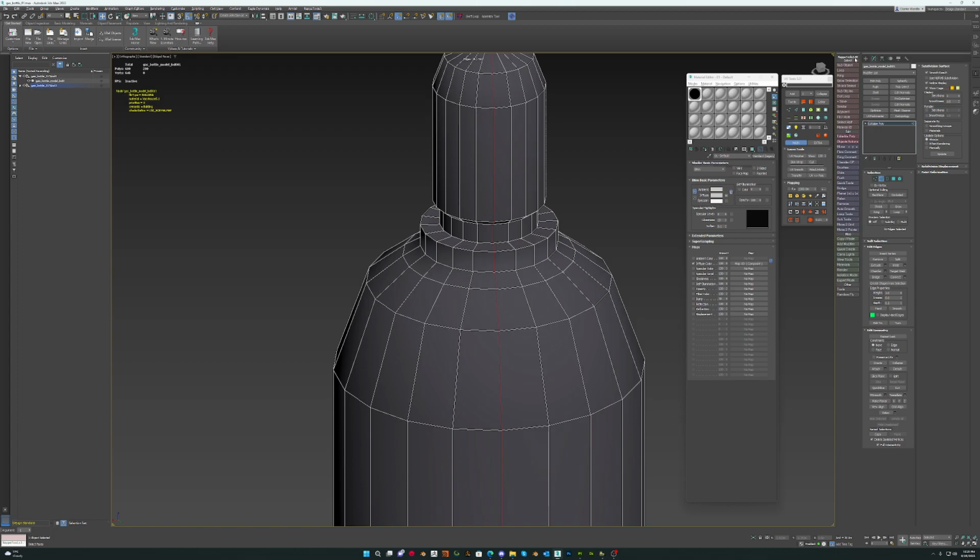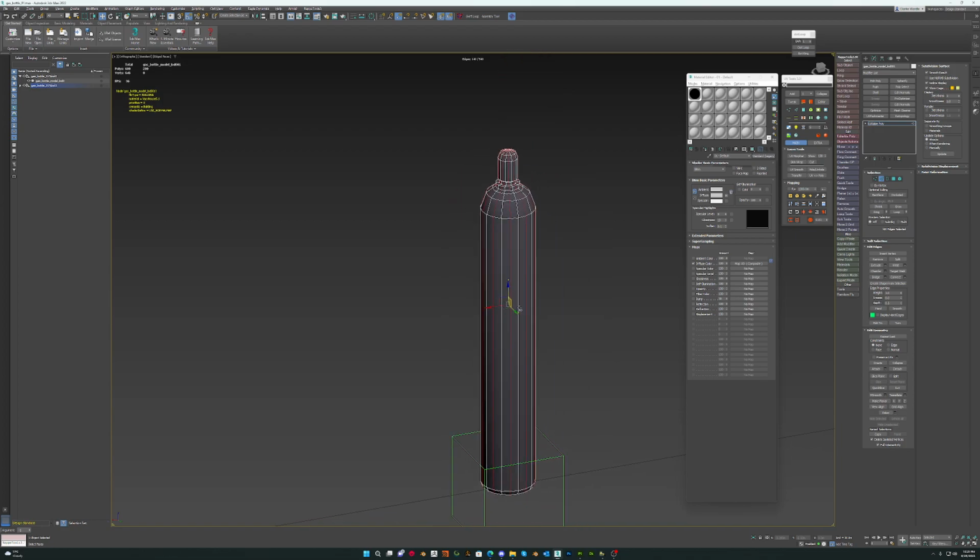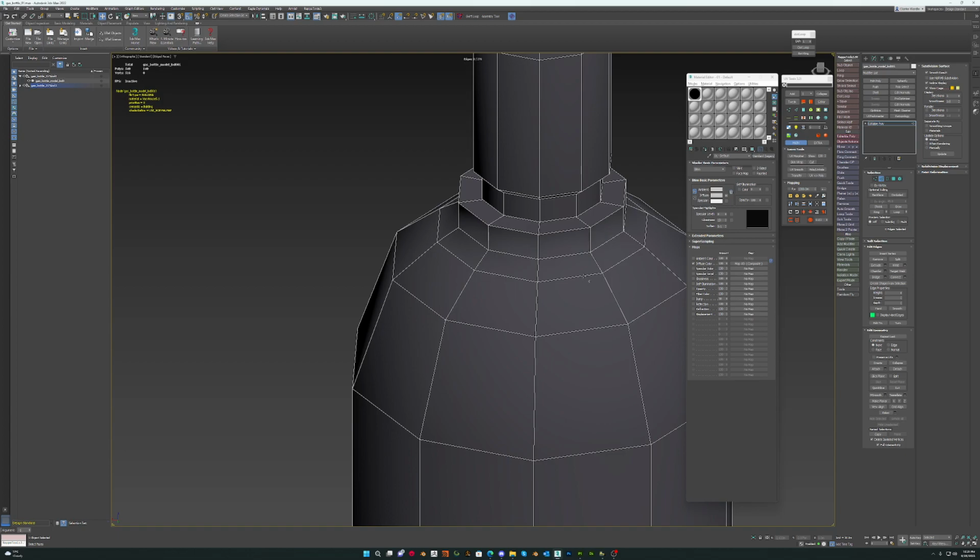Wrapper Tools is a really good plugin because you have something called dot loop. If I right click that and then say dot ring, it will choose every second line, and then all I do is remove them. Now I can see there's not really a transition between here and here, so I could probably get rid of that line as well.